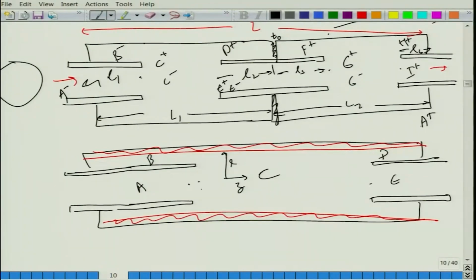Using this 2D representation, we can basically plot the P tilde R Z pressure field, we can get the RMS field plotted over this distance, similarly for this region, this region, this region, at a given frequency, and then we can do a frequency sweep to see how these pressure contours are behaving. So, you will see that whenever the peaks happen, very little energy will be transmitted downstream and all the energy will be reflected back, and at places where you get troughs, almost whatever acoustic power you are getting here, the same pressure contours will be here. That means the muffler is nearly transparent at that frequency, not much is happening. So, all these things can give you more insight into muffler design just when you look at the pressure contours.